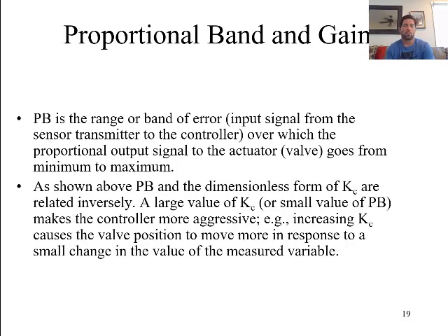Okay. One way that some controllers represent the gain is through the term called proportional band. Proportional band is just another way of saying gain in terms of a controller setting. You need to understand proportional band because some controllers that you might work on will have a setting of proportional band instead of gain. This works essentially exactly opposite. So I'll just give you some definitions.